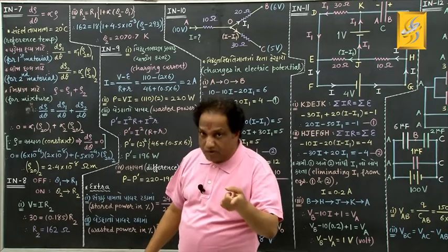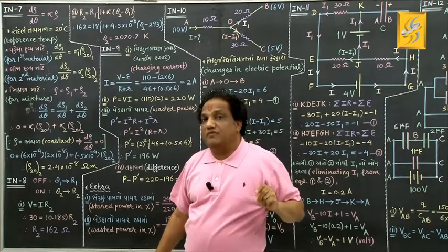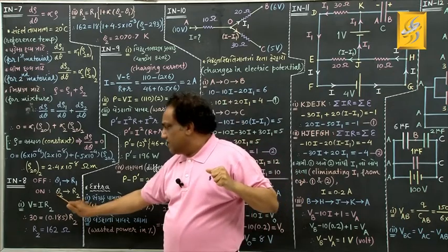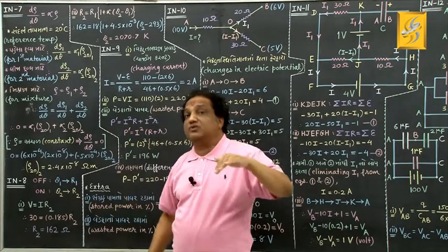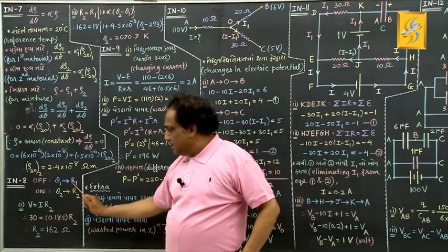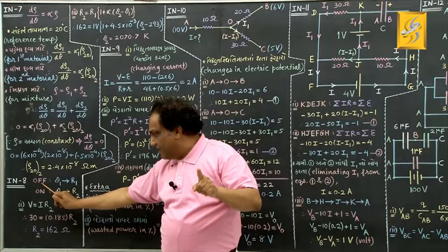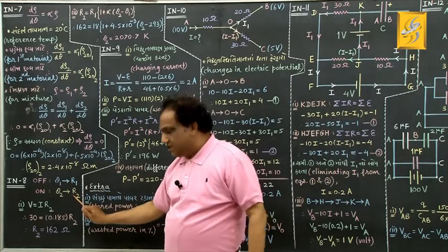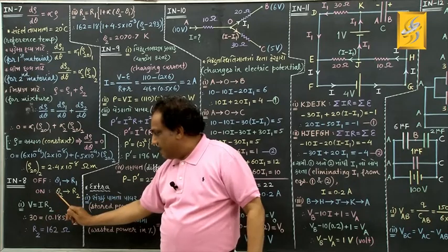But when you switch it on, that time current passing through the filament will raise the temperature of the filament. So, that time the temperature will be higher. That higher temperature in the on condition I am taking as theta 2, and at higher temperature the resistance also will be higher, let it be R2, correct. So, this is the resistance of the filament of the given bulb in the off condition at temperature theta 1, which is low, and this is the resistance of the same filament in the on condition of the bulb at higher temperature theta 2.